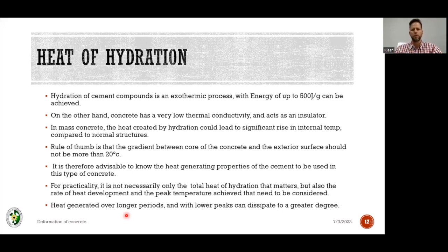If you go and you say, listen, I need a cement that's slightly coarser. So I'm putting that as a little seed there. The finer your cement, in other words, your 52.5s, 42.5s, will have a higher initial and ultimate spike of heat of hydration than would have your coarser cements at 32.5 or even at 22.5. Those aspects are completely different.